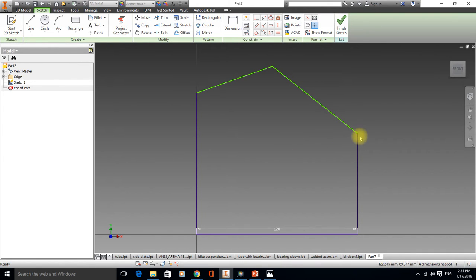Now, my two walls are going to be the same height. So let's put in a horizontal constraint. Top of that line, top of that line. They're now both the same. And let's hit OK. You can see as I drag one side up and down, the other side follows. My roof is still all wobbly, so he's OK. As I do drag it around, just notice if I go across the middle, you can see it's actually snapping to the middle of the bottom line. Okay, be careful not to do that for the moment.